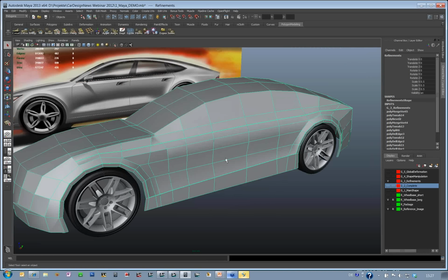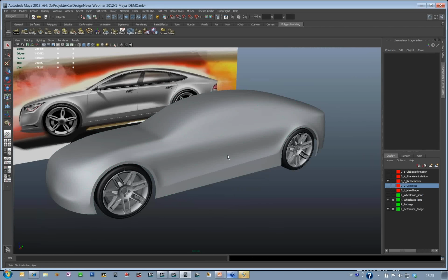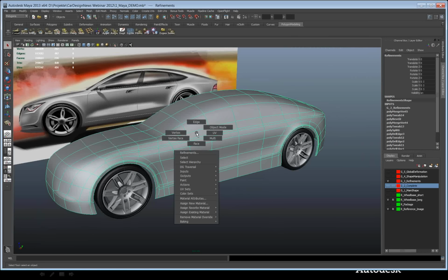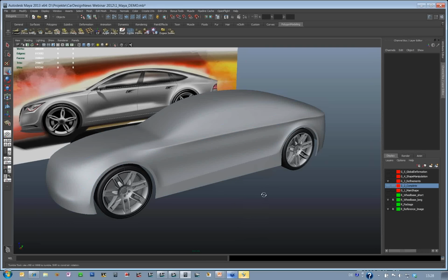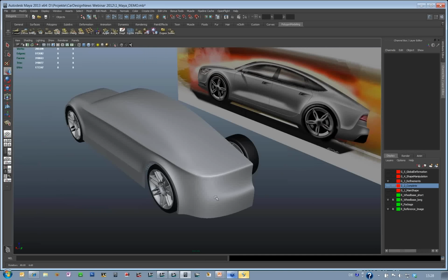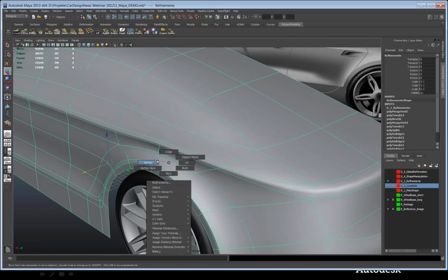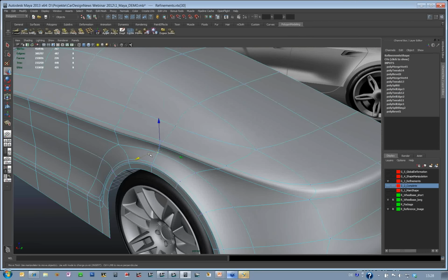So now I try to turn on the smoothing mode, and you see there's something there, but it's not so visible. So for this, I simply click and move on these faces just to get some nice sideline on the car. It looks like this. Of course, with this method you can adjust it additionally, so I don't need to be satisfied with this kind of distortion.